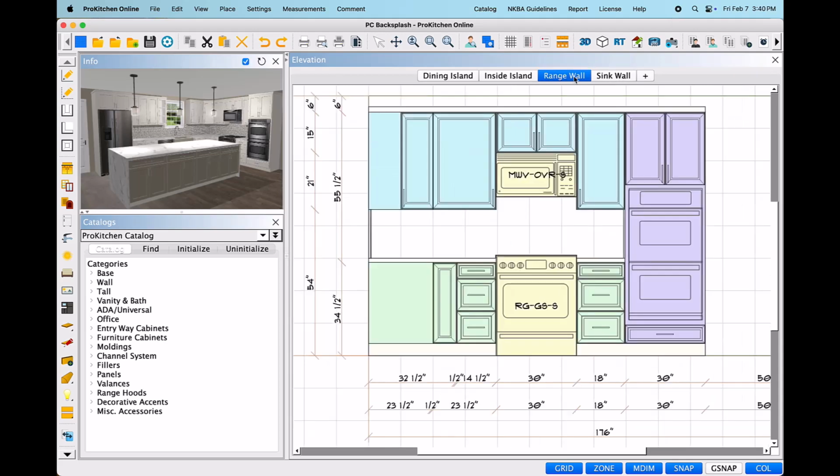Now let's move back to the range wall and take a look at Intersect. This tool is used as a fix of sorts for a miscreated set of intersecting lines. To demonstrate this tool, I will first need to create the circumstance in which it is used. I will use the third tool in the toolbox, Add Point, to provide us the opportunity to utilize Intersect. Add Point will provide you an opportunity to add an additional point along the selected line.